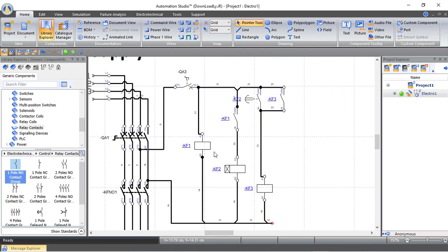Let's get back here. This relay, when it's working, will close this point, which will make this timer start counting. Let's say that this on delay timer will work after 10 seconds. So after 10 seconds, it will close this normally open contact, which will make the contactor work. So the power will move on and go to the residential loads. And this normally open contact from the contactor will also be closed.